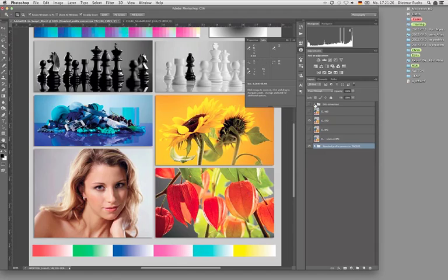And therefore, if I'm looking here, I've created a DeviceLink with exactly the settings that the automatic option was choosing, and that's this setting. So still an improvement over the normal ICC conversion. But with my personal setting, where I defined myself, I want this maximum red, for example. Look on this area here, where this maximum red comes in. I get a much higher saturated red on my output. But this is not an automatic calculation. This is my personal feeling that this image would be better if I use this option.